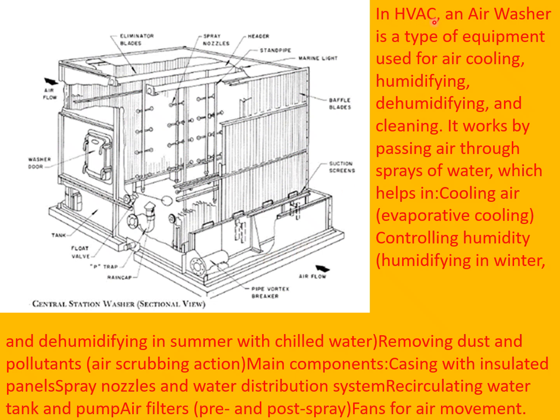In HVAC, an air washer is a type of equipment used for air cooling, humidifying, dehumidifying, and cleaning. It works by passing air through a spray of water, which helps in cooling air, controlling humidity, and dehumidifying in summer with chill water, removing dust and pollutants. Air scrubbing action.